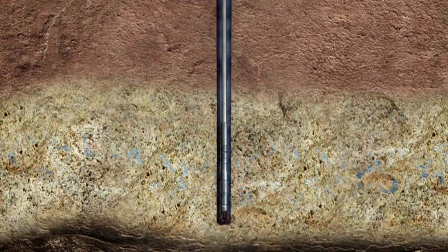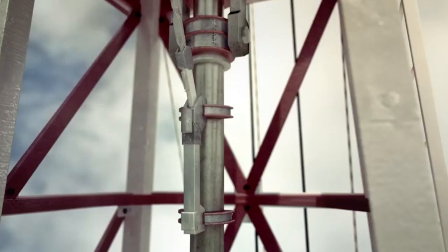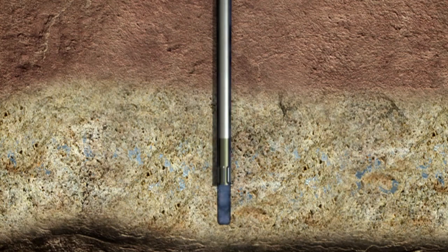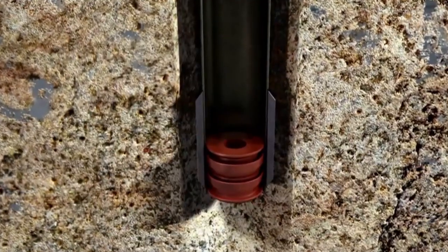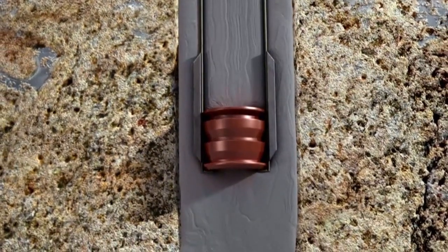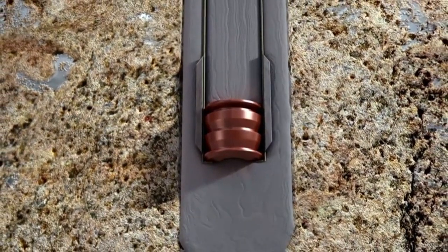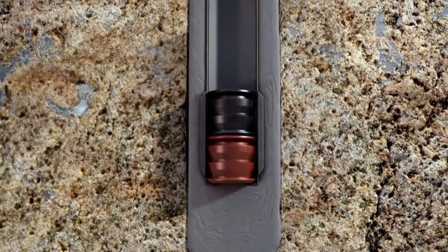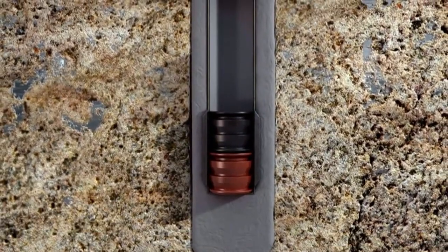As we drill deeper, we encounter different levels of pressure, so we need to isolate certain layers to continue to ensure total well integrity. To achieve this, a surface casing is initially inserted. Cement is then pushed through the casing using specialist plugs that allow the cement to flow out through an opening at the bottom before setting in place to provide a sealed wall of steel casing and cement sheath between the earth and the well hole. This isolates the surrounding environment, including any intersected aquifers.